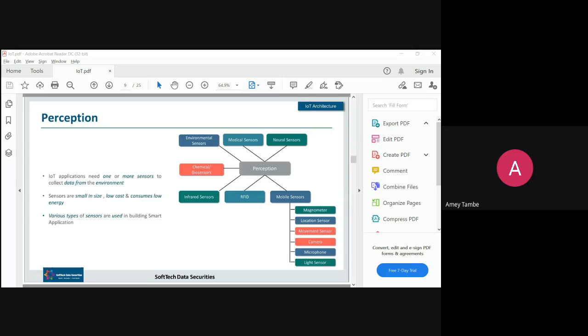But if we set the sensitivity very high, then the slightest change in the current environment in which the sensor is deployed, if it is getting some warmness, it will automatically trigger itself. Like yesterday when we were dealing with the sensor, I switched off the flame, and after that some warmness was there at the stick, and the sensor was still reacting to it. Why? Because I had set the sensitivity to a very high level with the potentiometer on the sensor. So we need to set our sensor not below average and not above average.